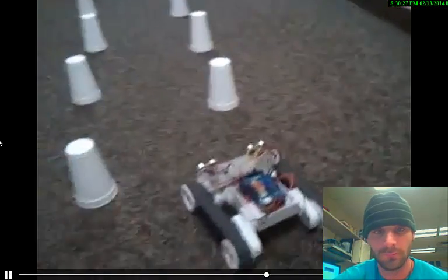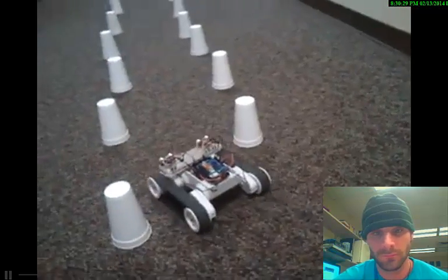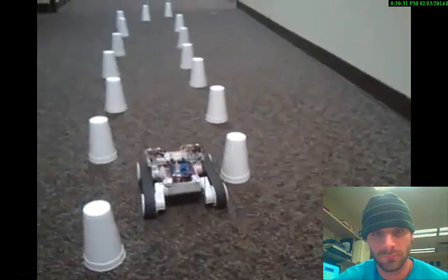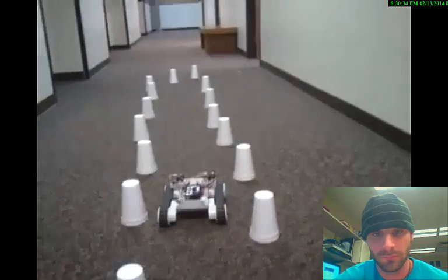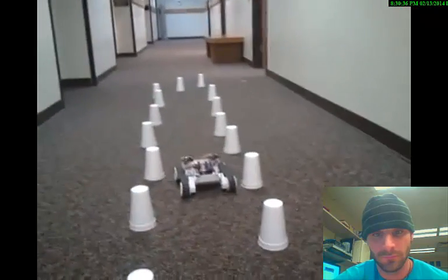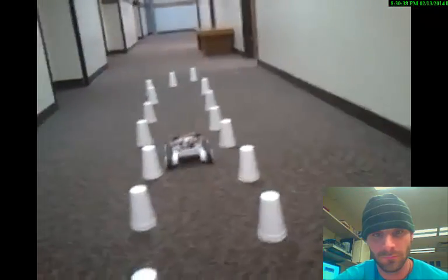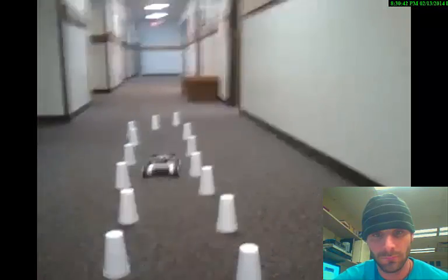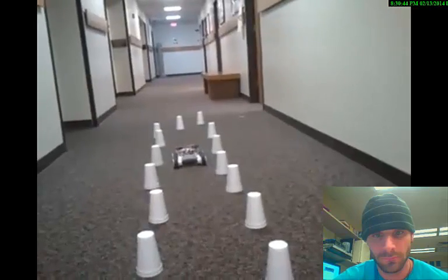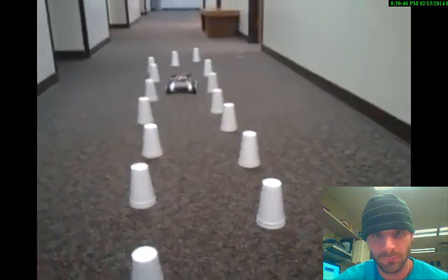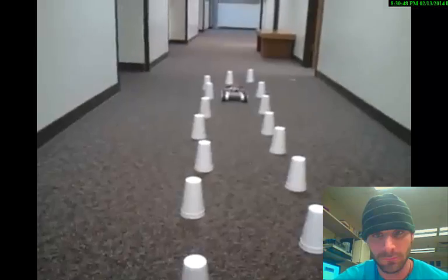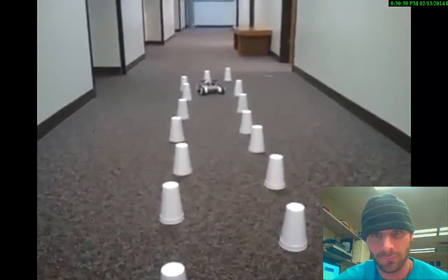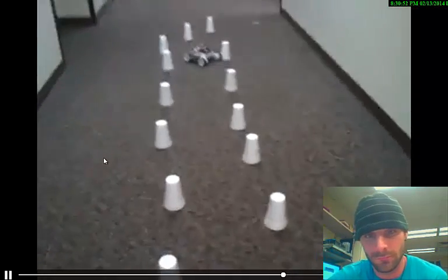I'm going to set his tolerance to 10 centimeters. And if he gets within 10 centimeters of something and sees it on his IR, then he's going to be able to go ahead and turn and adjust right there. So he will, in theory, never actually hit a wall and never be in that issue. Then, once I come up with a better way for him to figure out how to actually get out of a corner whenever he gets in a corner, I need to figure out a way for him to actually localize and know at all times where he is.